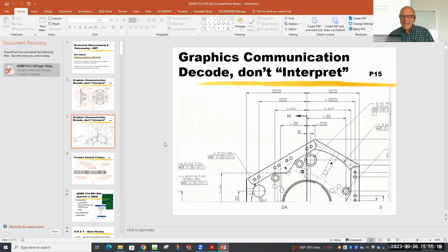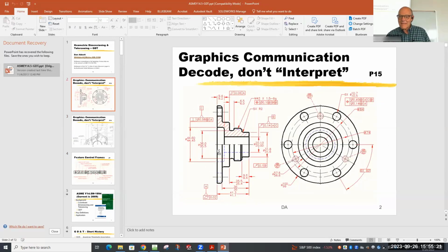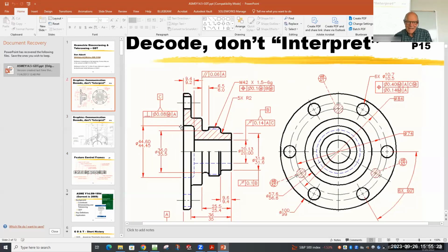I'm going to go back to this. So you'll notice right here, that pocket is going to go over something. There's a dimension on the pocket, and the dimension on the pocket is an upper and a lower limit. Up here, it tells you something that's less limiting than positional tolerance. It tells you that the axis of that pocket, that little axis going down through here, has to be perpendicular to something. And the something, when you look down here, is identified as the letter A.